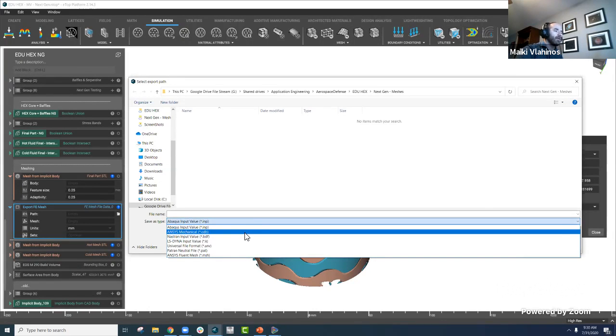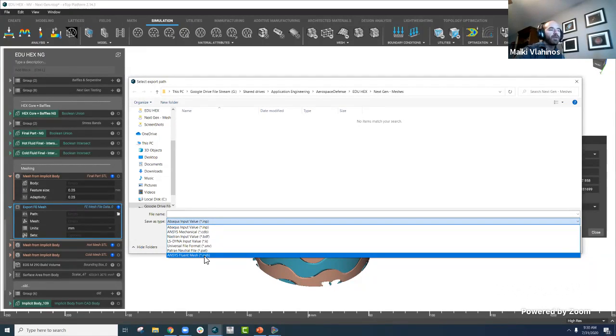Otherwise, you can get to Ansys a few ways. You can use the Ansys Fluent Mesh. The way I've done it before is through ISM CFD, which is a part of Ansys. That just helped me clean up the mesh a little bit, as well as define the inlet and outlet boundary surfaces.